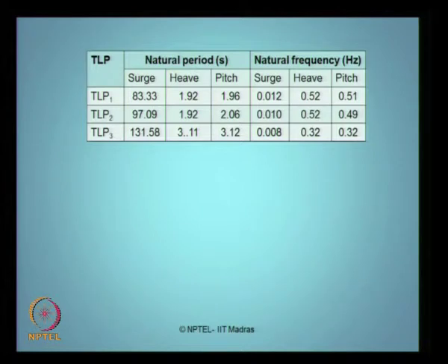So, look at the frequencies in hertz for heave degree of freedom, it is about 0.3 to 0.5, okay. But surge is very low, very large time period. Pitch and heave are relatively the same, okay, stiff degrees. So, we have these geometric characteristics of this problem.